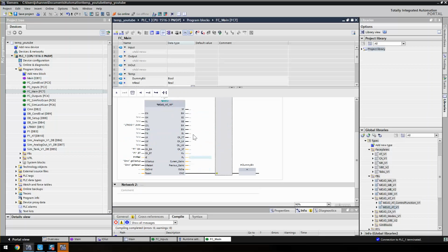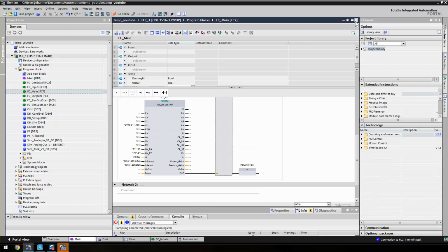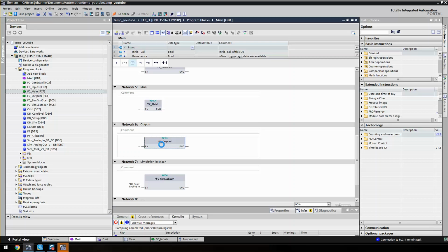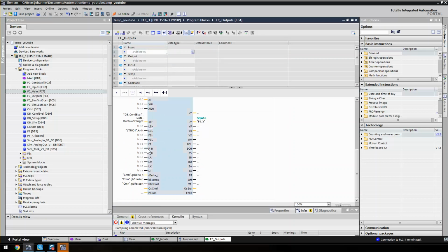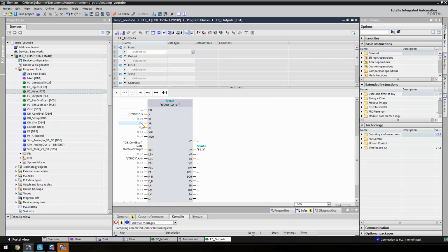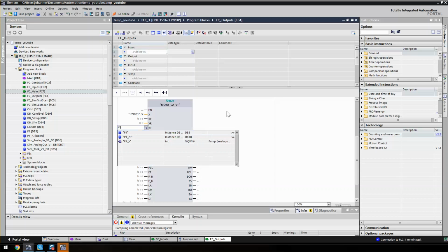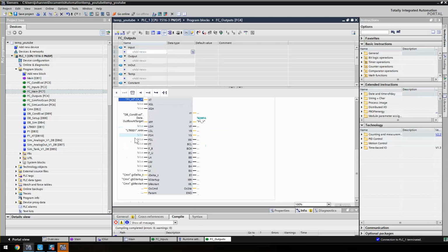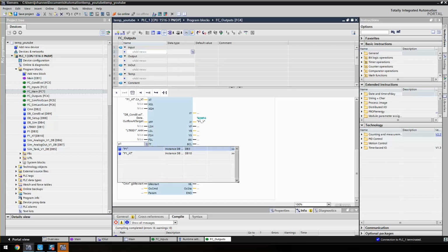Let's go to where these outputs are used as inputs instead of mapping them here, just to make it more structured. Which is here. So the Autotuner gives out a maximum and minimum manual input or a tracking input. So we'll put the CA in tracking automatically. The Autotuner does that. And then put it in tracking. This will be the tracking value. This will force tracking. That's one way to do that.